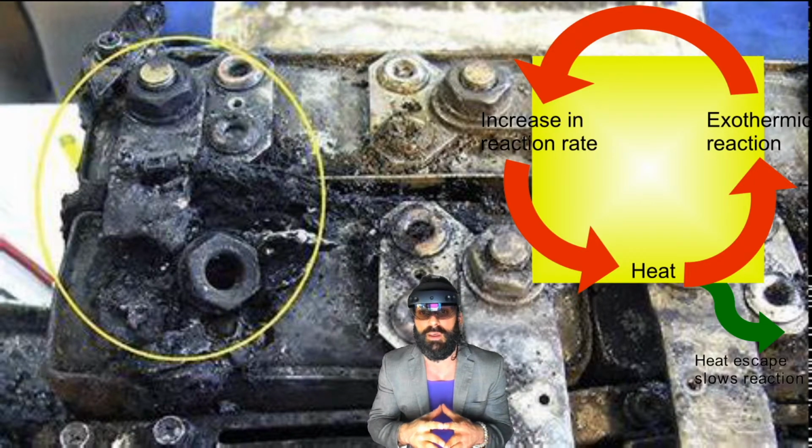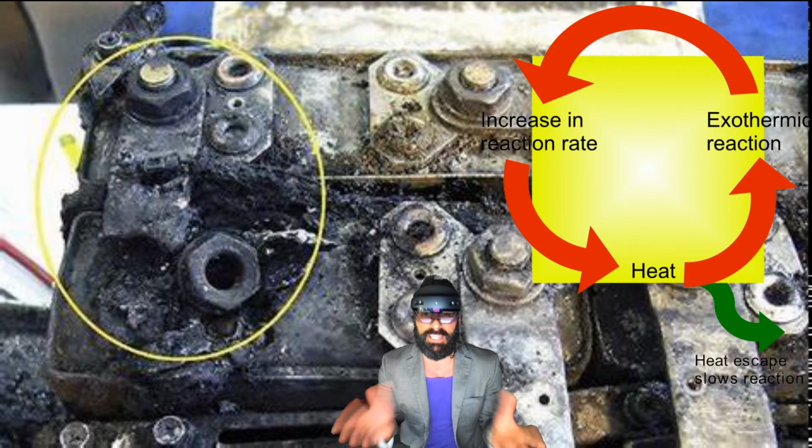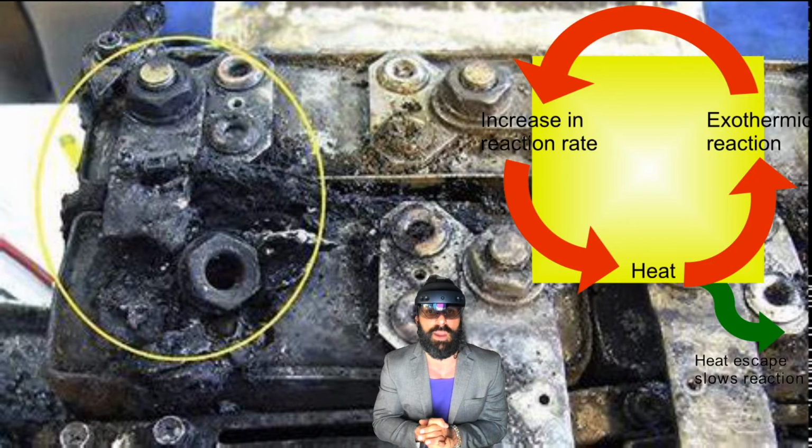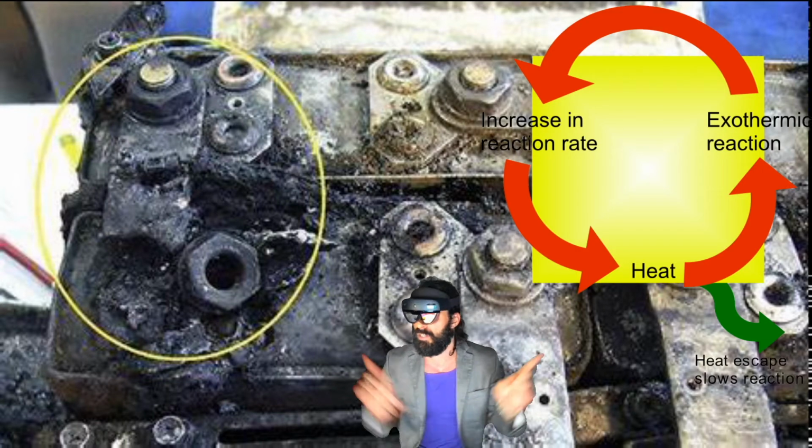When the temperature elevates, an exothermic decomposition of the cell material begins, and eventually the self-heating rate of the cell is greater than the rate at which the heat can be dissipated to the surrounding area, and the cell temperature rises exponentially, and the stability is ultimately lost. Now, the loss in stability results in the remaining thermal and electrical chemical energy being released into their surroundings. You can actually see that here.